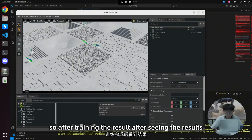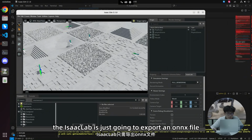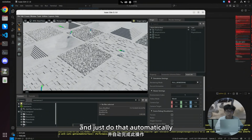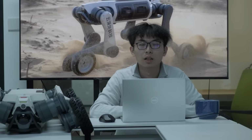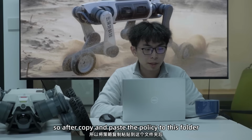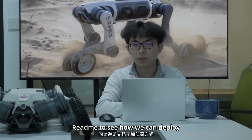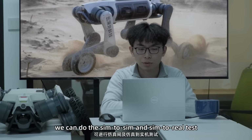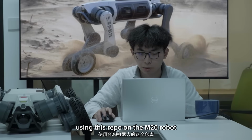So after training, after seeing the results, playing and visualizing them, Isaac Lab is just going to export an ONNX file pretty easily. You just do that automatically, and we can use it to deploy to the real robot. After copying and pasting the policy to this folder, let me go through the README to see how we can deploy. We can do the sim-to-sim and sim-to-real test using this repo on the M20 robot.